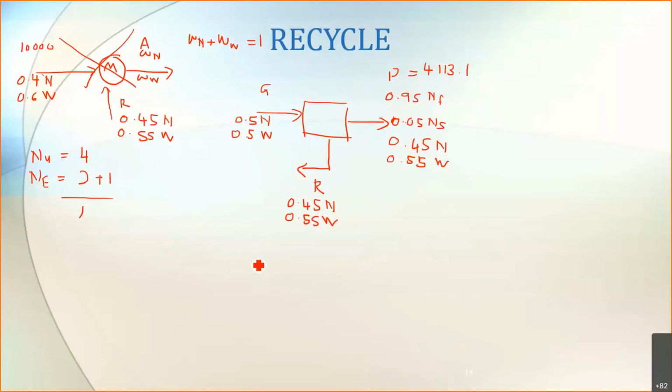So again I do degree of freedom. Number of unknowns is equal to 2. I have two species, NaOH and water, so number of equations is equal to 2. So I will have degree of freedom equal to 0. So based on this, I can actually solve for this system and find the value of R. You can do a balance on overall, on water, or on NaOH.